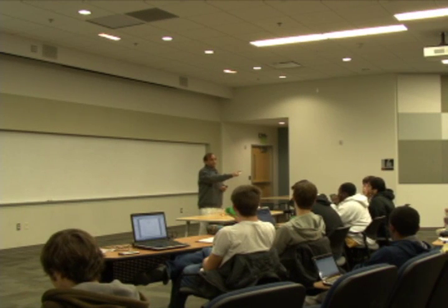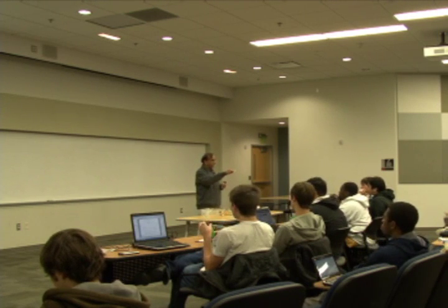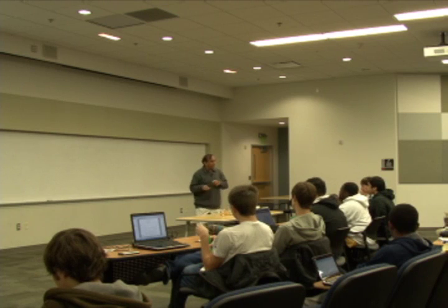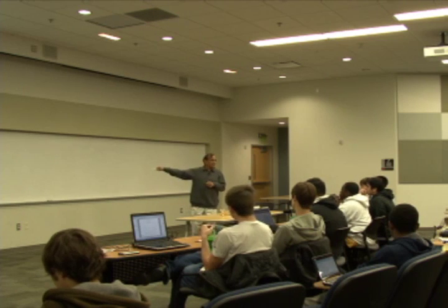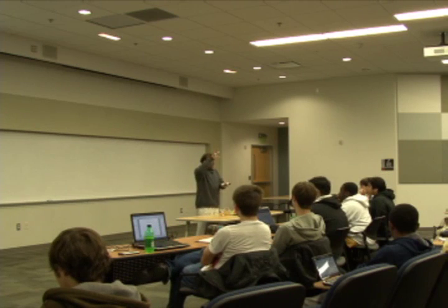Zoe has a fantastic question, and that is, now we are saying Z-bit is going to be part of the address into a ROM, right? And so what you have to make sure is, the only time that it really comes into play is when Z is 1, right? When Z is 0, it's a normal thing. So you can think of the ROM being divided into two halves.